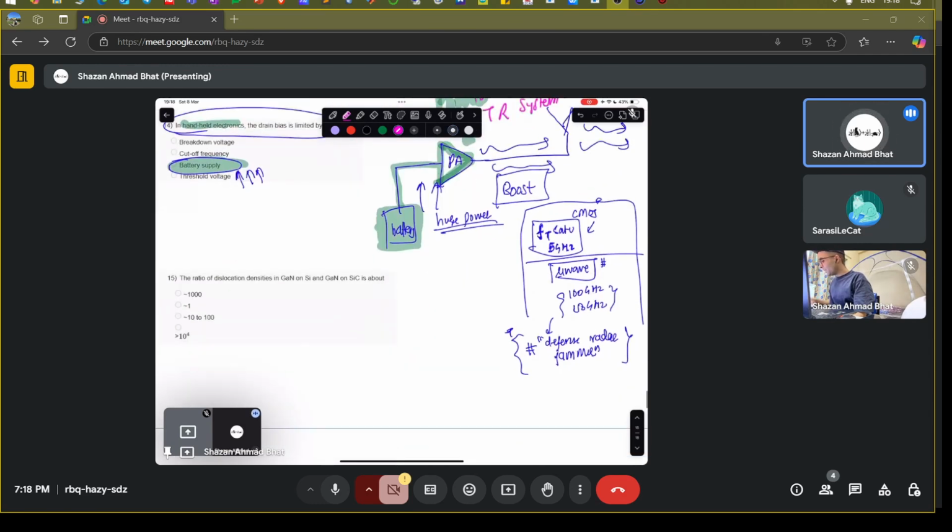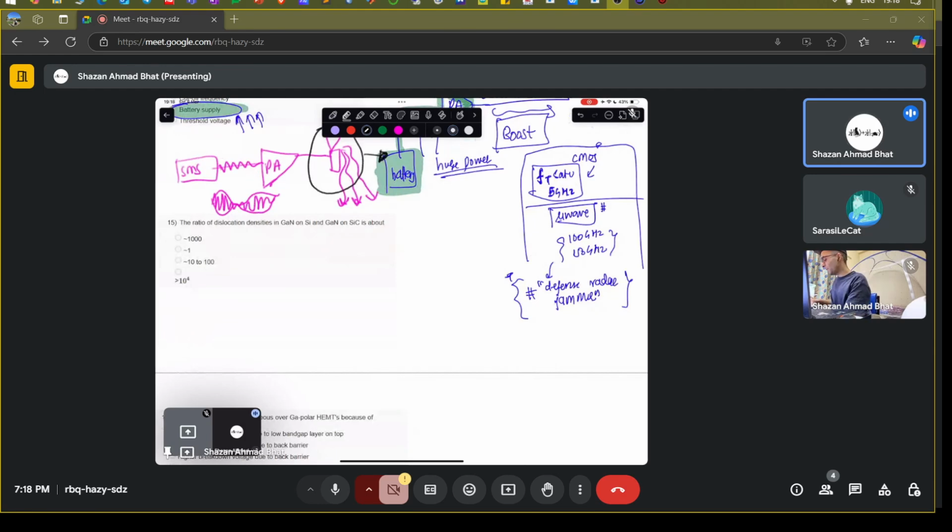Because whenever you send a message, let's say an SMS, it gets converted into a signal, a carrier frequency and the envelope frequency. Then that is transmitted via the power amplifier and given to the microstrip antenna, which throws it into space. Throwing it into space using electromagnetic waves uses a lot of power. This is the region where the highest power is thrown out of your system, and that power comes from the battery itself. That is why the radiation levels are important.